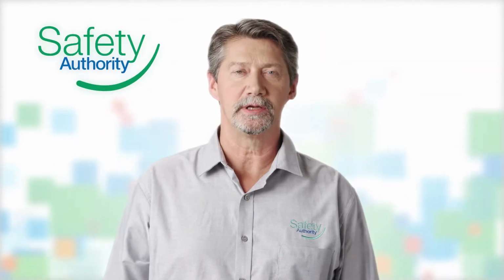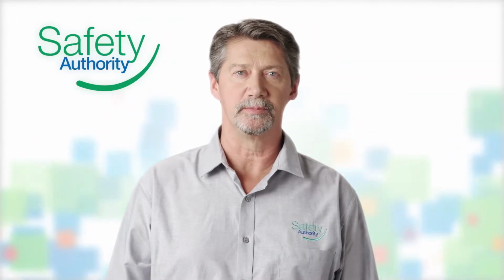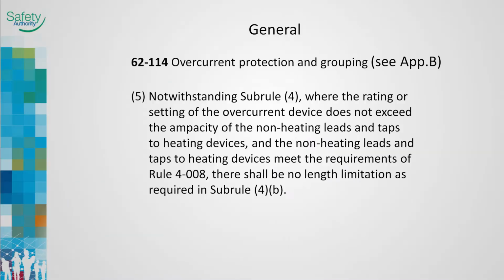Subrule 5 recognizes that some heating devices can be supplied with custom leads. These leads must be fully rated to the circuit which supplies the heating device. When this is the case, there is no length restriction provided the leads and taps are suitable to be run in the installation environment in compliance with Rule 4-008. This subrule now aligns heating device sets with the existing allowances in Rules 14-100 and 14-104.